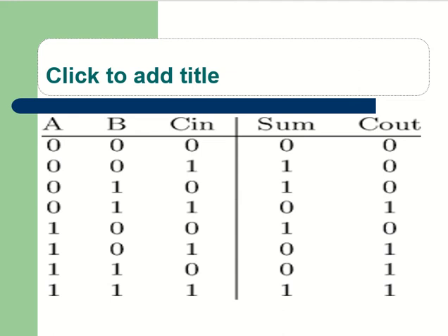Now with this information, let us move on to the design part of it. As I said, before designing, first we have to generate the expression for sum as well as the expression for carry. So first we'll get the expression for sum and carry from the truth table, and from that let us design the circuit for full adder. To write the expression for sum, first we have to see where all the output has become 1. So from this we can see here 1, 2, 3 and 4 cases. In 4 cases the output has become 1.